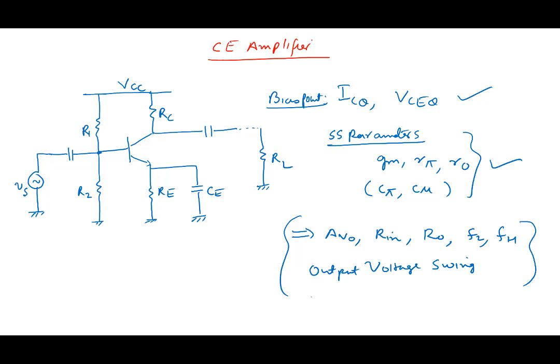And we had also said that once you calculate these values, this amplifier can be represented, at least in the mid-band region, by Rn, plus minus AV0 times Vin, and R0. These values that you calculated, AV0, Rn and R0, you can use to make a new circuit which is the equivalent circuit of the amplifier. Rn here, the voltage here is of course Vin.